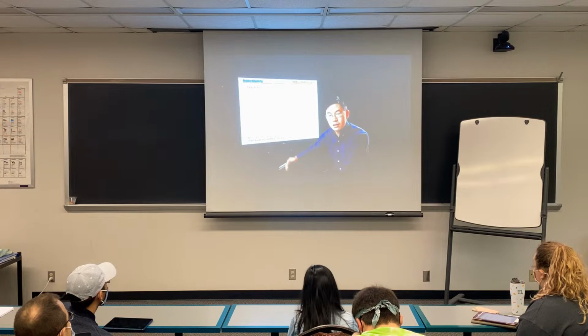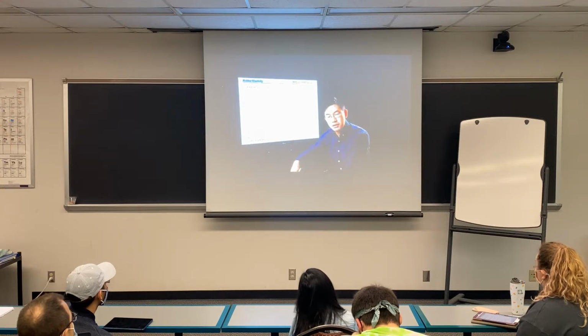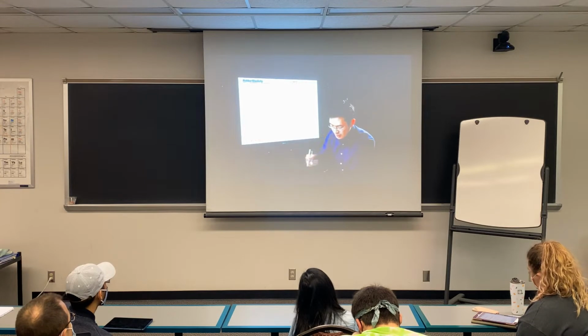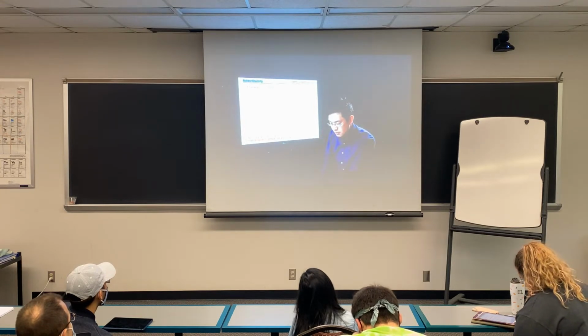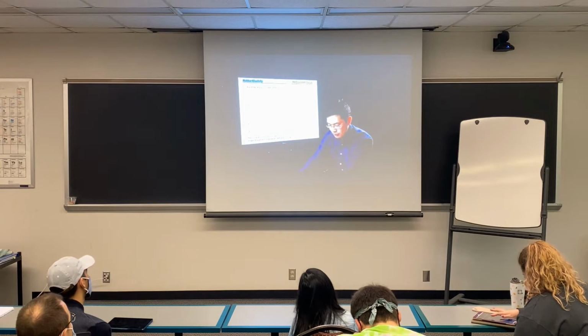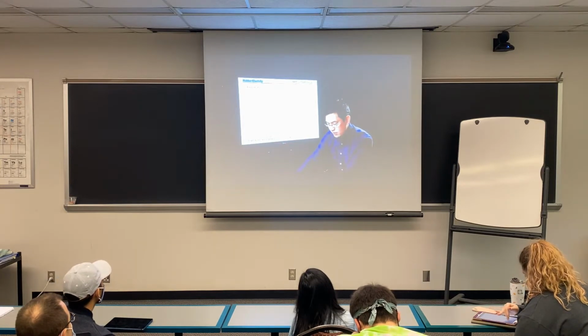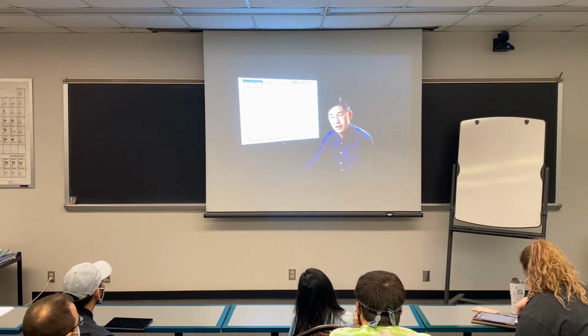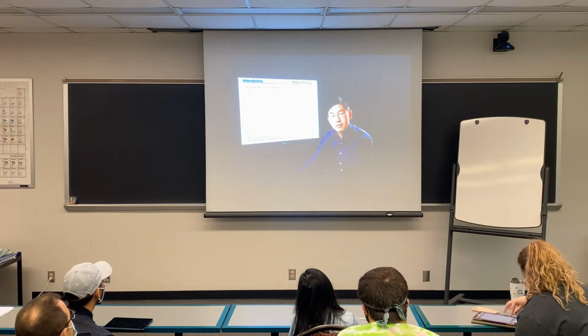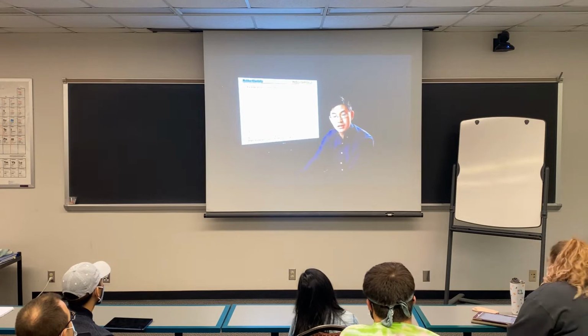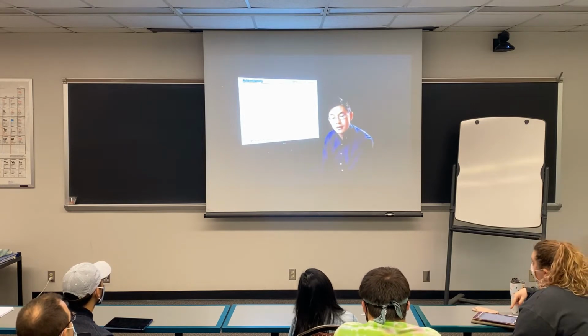This is something like our osmotic pressure measurement of the second virial coefficient and molecular weight, but here it gives you C1 and C2. So you can extract the C1 and C2 values, and this is a good empirical approach that gives a much better fit to the experimental data in rubber elasticity theory. Okay?